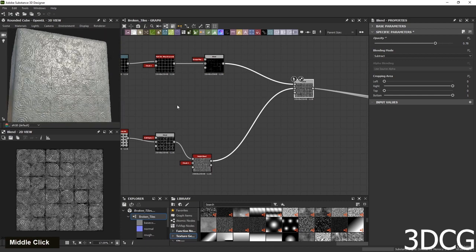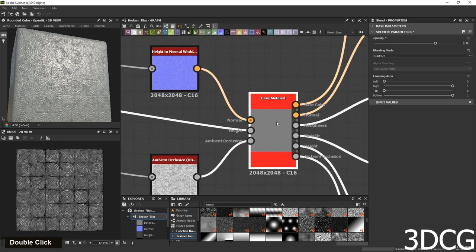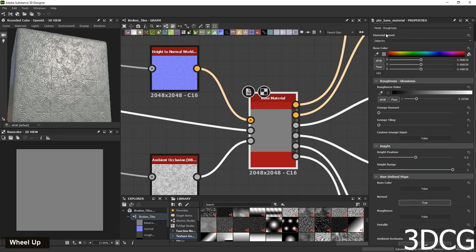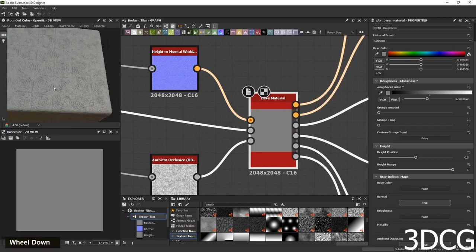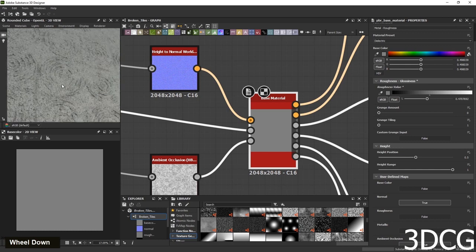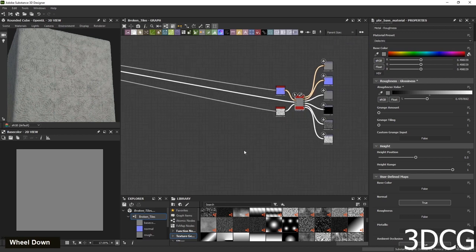A little bit glossy, so let's go to original base material. We didn't expose the roughness, so we have control over roughness through the base material option. So let's add a little bit roughness towards white, something like this. All right, nice.